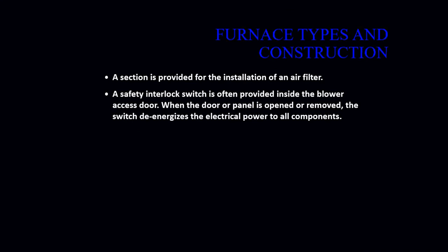We call that a safety interlock switch, or a dummy switch in many cases, because we want people, especially homeowners, not to be messing around with the electronic devices, especially if they are not qualified to. So the door switch needs to be engaged in order for the furnace to be on. In other words, the blower door needs to be put back onto the furnace in order for it to start up again.